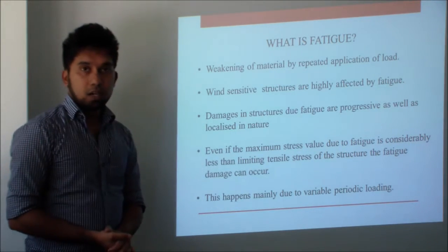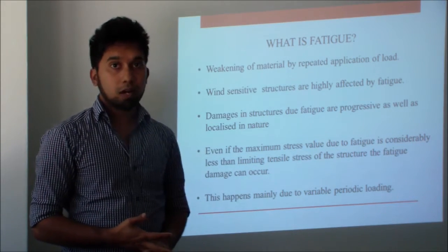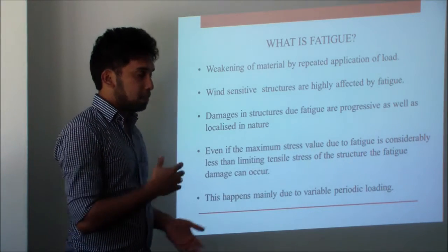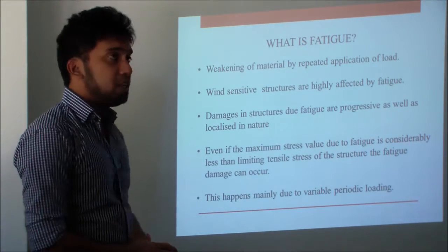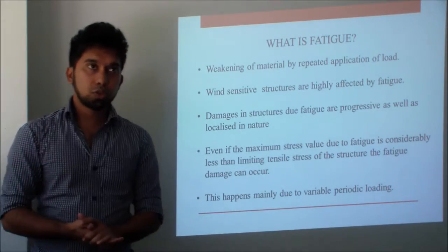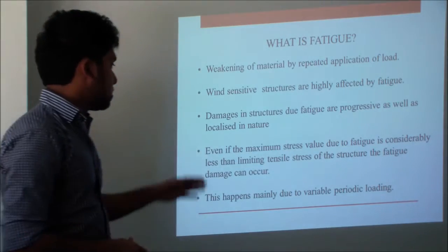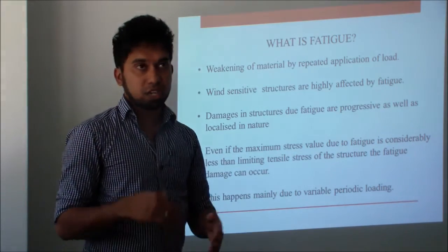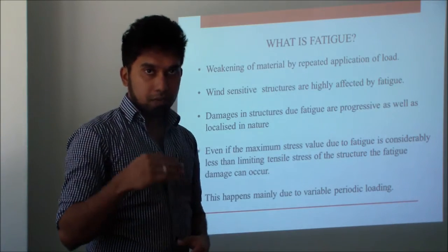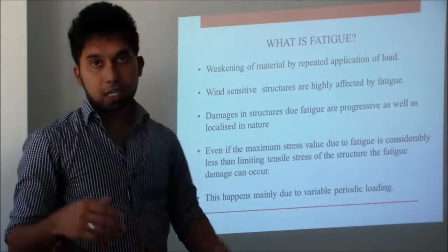The damages in the structure due to fatigue are progressive as well as localized in nature compared to other damages that can happen to a structure. Even if the maximum stress due to fatigue is very much less than the maximum tensile stress that the structure can take, fatigue damage can still occur, because of variable periodic loading.